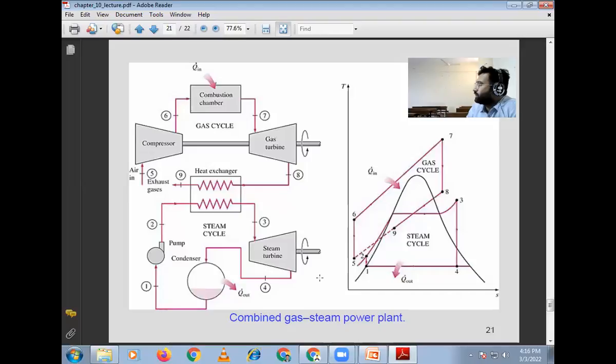At the end of the semester or throughout the semester, you can go for it. Learn the basics and create a program such that the program will ask what is the boiler pressure, what is the condenser pressure, and the condition of steam at turbine input. If you give only these 3 inputs, then it should give you the cycle efficiency, the specific steam consumption, the work ratio, all these parameters, just by giving only 3 inputs. The numericals which we spent 20 minutes solving will come within a fraction of a second. So you can check for that also.